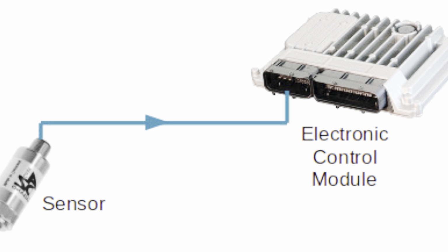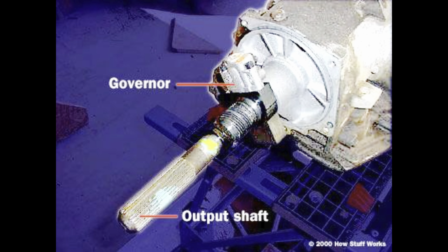Another advantage to these smart transmissions is that they have a self-diagnostic mode, which can detect a problem early on and warn you with an indicator light on the dash. A technician can then plug test equipment in and retrieve a list of trouble codes that will help pinpoint where the problem is. Governor, vacuum modulator, throttle cable. These 3 components are important in the non-computerized transmissions. They provide the inputs that tell the transmission when to shift.